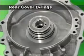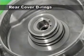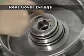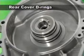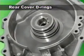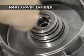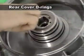Among the 4 D-rings installed at the rear case, the 2 upper rings are to prevent the leakage in oil supply to the overdrive clutch. If these are damaged, 3rd speed or 4th speed driving may be impossible due to the oil leakage. The 2 D-rings installed at the lower part of the rear cover are to prevent the leakage in oil supply to the reverse clutch. Therefore, when damaged, there may be trouble in reverse clutch operation while backing up.